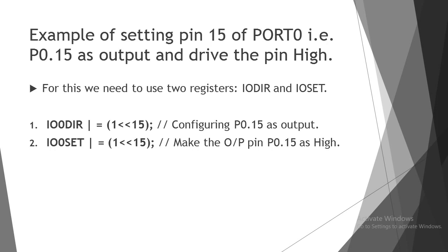Now we have to send the high pulse, logic 1. So we will write IO0SET |= 1 << 15.